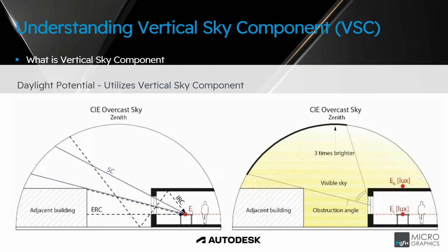Some countries have legislative requirements to ensure adequate daylight, while most have informative codes and standards requiring sufficient daylight without mandatory levels being defined. Forma uses BRE's suggested threshold to predict daylight performance. The thresholds are targeted to predict an average daylight factor of 2%. VSC default threshold given a target of 2% daylight factor.